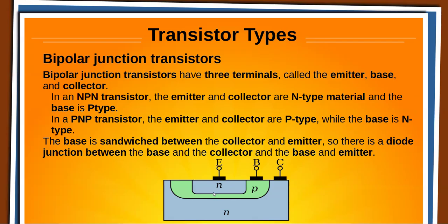The amount of current that flows through either an NPN or PNP transistor would be essentially the same current going through the emitter as going through the collector, right? No. Collector current will be less than the emitter current. Remember, the emitter current is the collector current plus the base current.